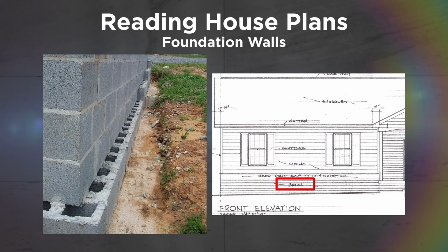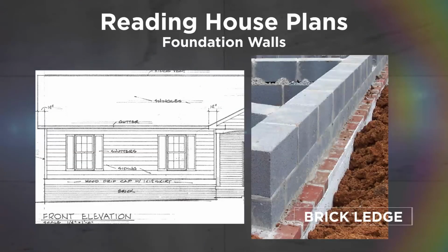Instead, it will be a brick veneer on 8-inch block, but the 12-inch block gives support to the brick all the way into the footing. Here, we notice that the brick has been waterproofed at and below ground level.